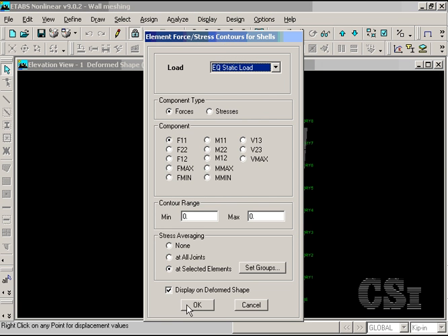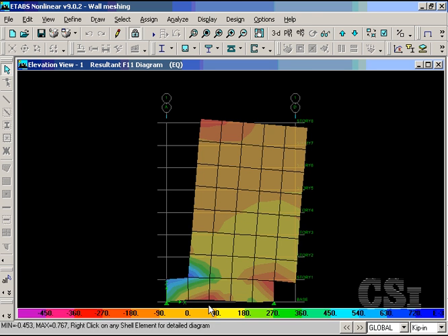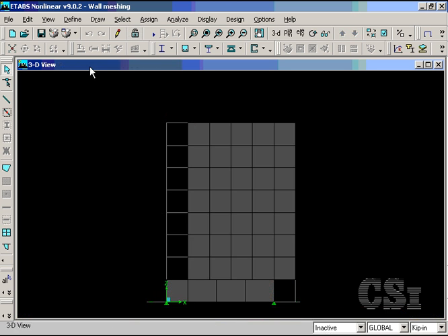A plot of the forces in the wall shows a pattern that seems appropriate, with the expected concentrations around the corners. In the next analysis, we will use a mesh that does not line up in the interior region, but does provide connectivity at the corners. This connectivity at the corners is very important.